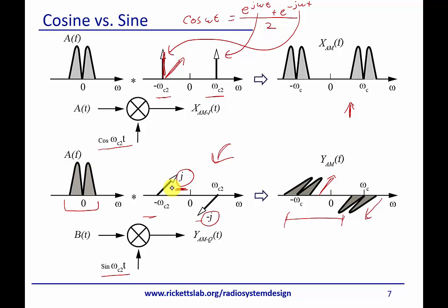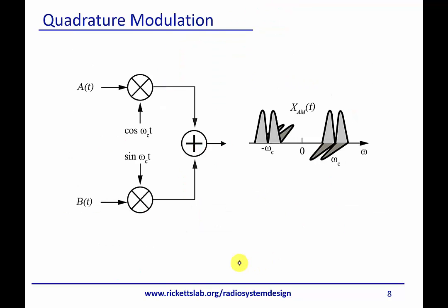Because if you look at these two signals, what would happen if we tried to put the two on top of one another? Here all I've done is taken a signal from before and added the two together. You can notice I've got my cosine signal here and my sine signal there. I've drawn it this way because graphically you could say, I could actually transmit these two signals, and if they're orthogonal, because one's real and one's complex in value, and once again all that means is one is phase shifted from the other by 90 degrees, I can actually transmit both of them at the same time and not lose any information.